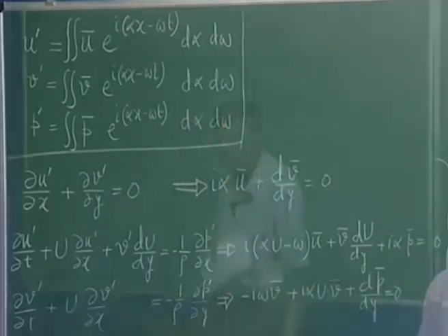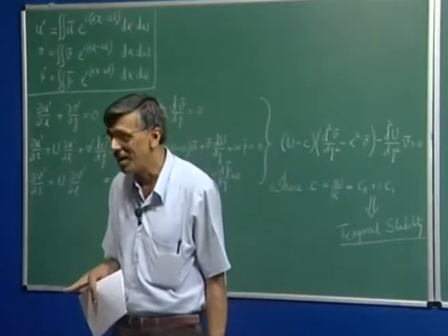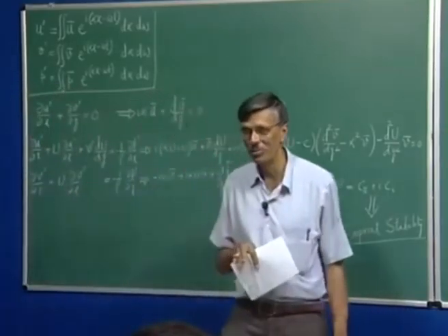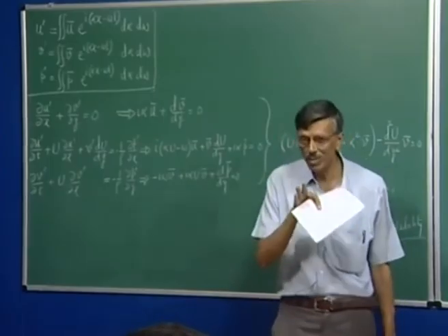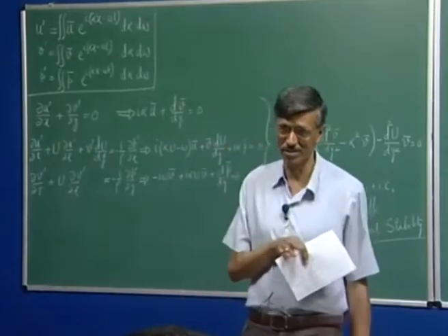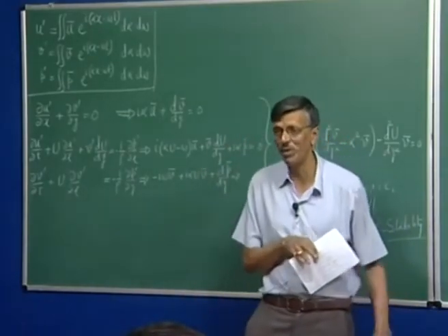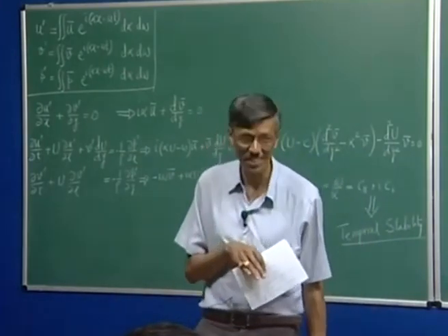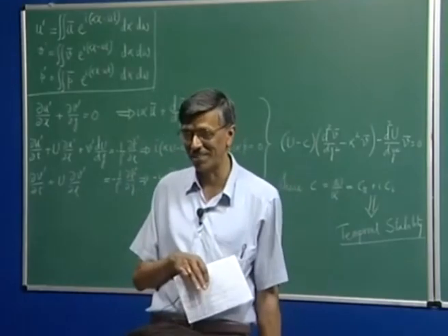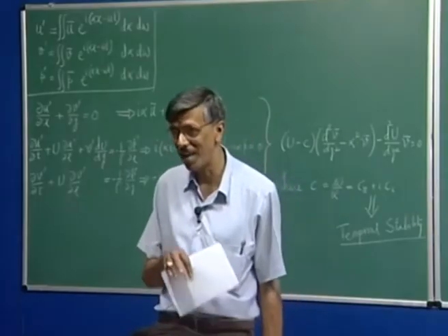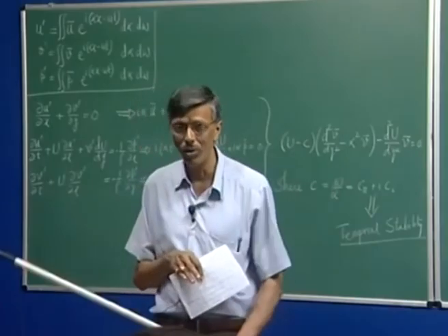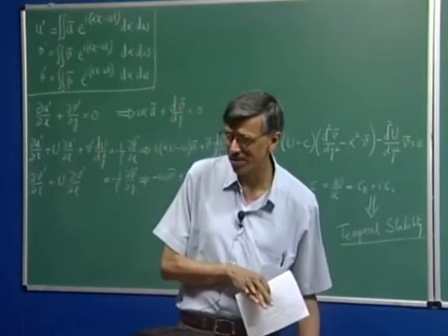So, if alpha i is positive and you are talking about x in the positive direction, then that would correspond to the stable solution, that will damp the solution. But please be aware that a priori you do not know if the disturbance has to go in the positive x direction. It can go in the opposite direction, negative x, right. If it does so, that same alpha i which I called stable for a downstream propagating disturbance will become unstable for an upstream propagating disturbance.